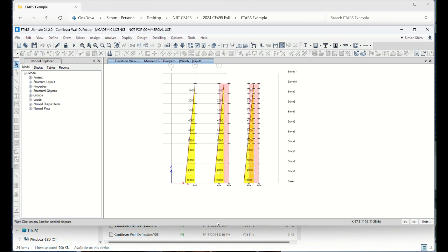Most likely, assigning loading, reactions, and boundary conditions, we follow the global coordinate system, X, Y, Z. But for local members, each member doesn't always have to follow the global axes. Because if this column is extended, they are not matching, right? So we need to understand the global coordinate system and your locally oriented member axes later on. But for now, this is 2D.